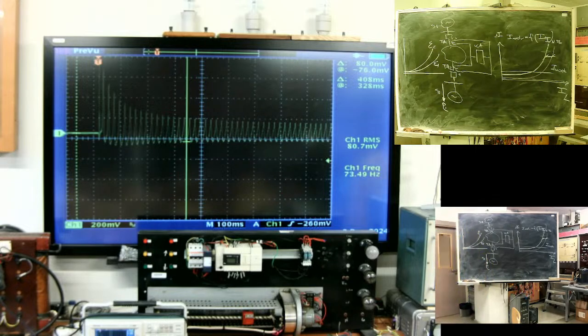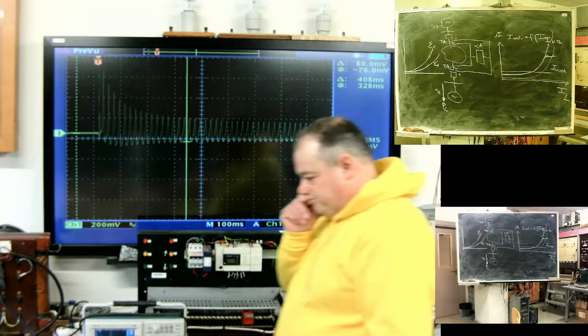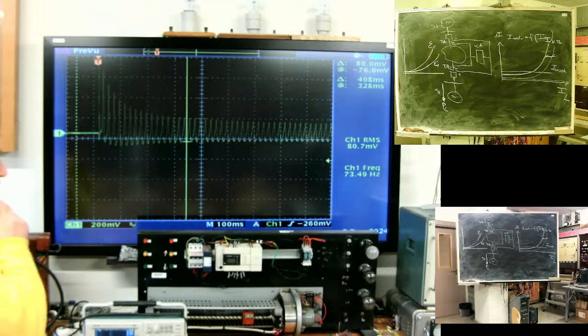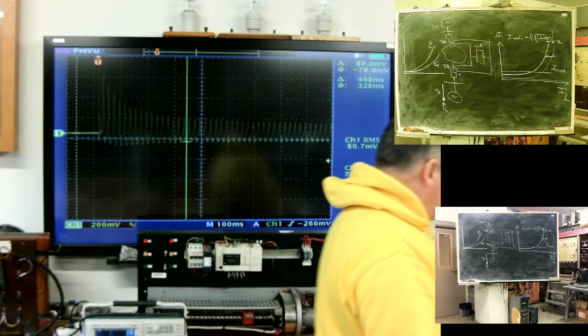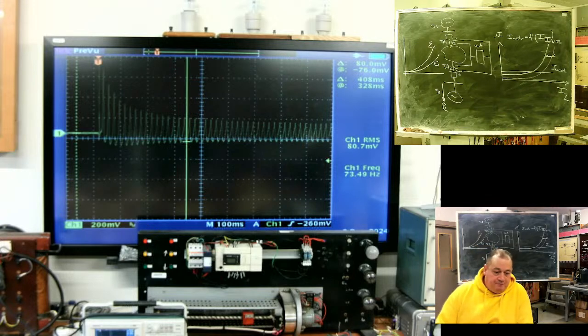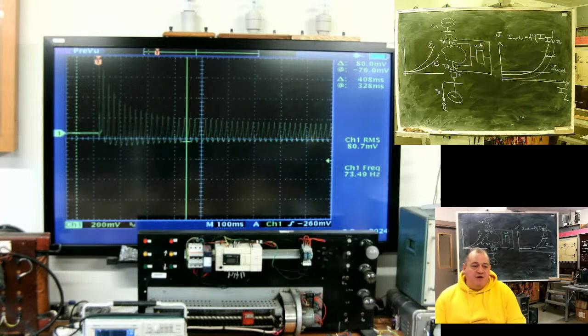The problem of inrush current. If you do nothing, your protection will falsely operate, because this current exists on the primary side, but there is no such current outside. It's not outflowing. This current is going inward. Maybe you can think of a solution, what to do: delay operation, just delay operation till the transient ends. It's a very bad idea, in my opinion.